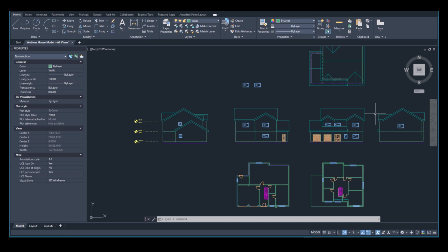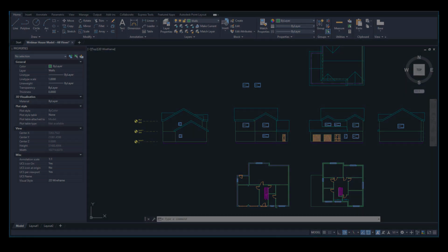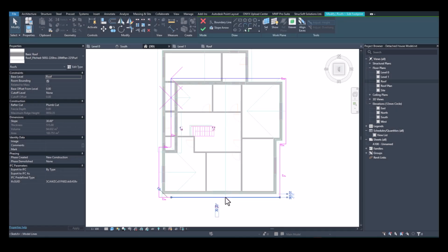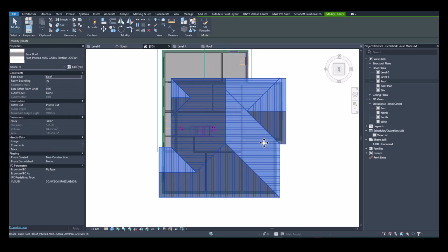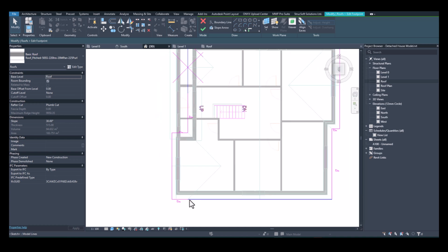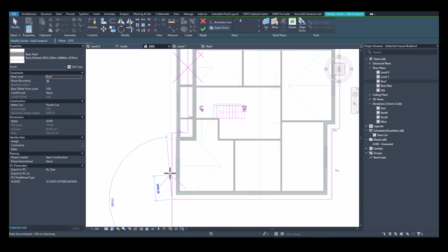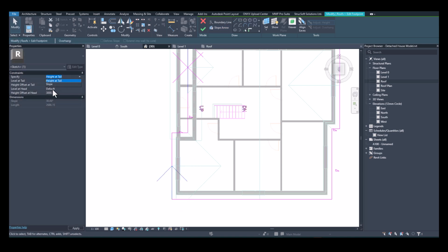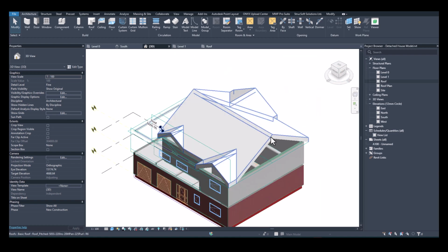we have a straight roof left to right in that case. So I need to go back to Revit, where I can make sure that we don't define a slope on this edge. I'll just uncheck this one. Okay. So I'm going to remove this one, and I just need to use a slope arrow there instead. There you go. I want this to be 30 degrees. Okay. And there we have our roof.